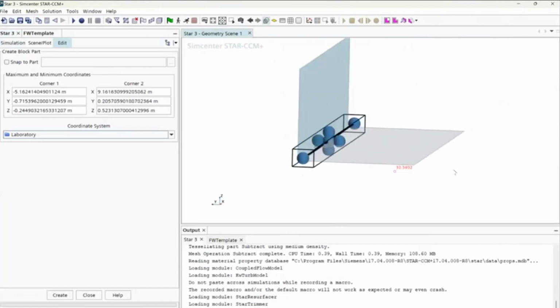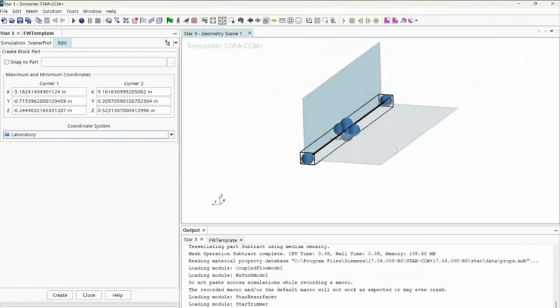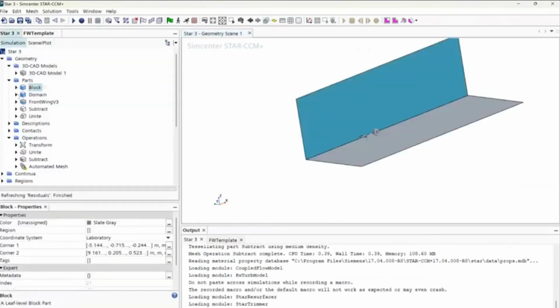Well, this is the lane where pretty much wherever the geometry is. We want to keep this lane consistent, because if you don't and you just make it like this, you're gonna have errors doing wacky stuff. We go from huge mesh out here to very small mesh. We want to keep this lane consistent. So let's create that, and we're going to rename it detailed lane.